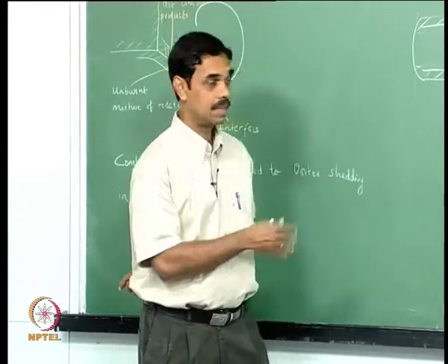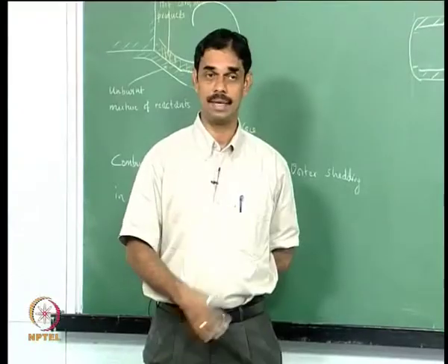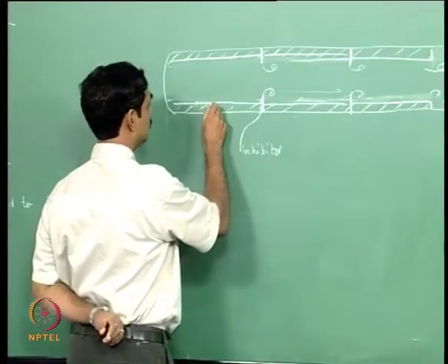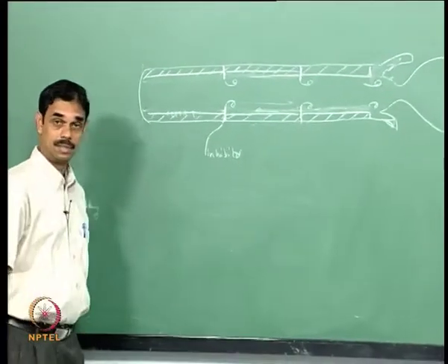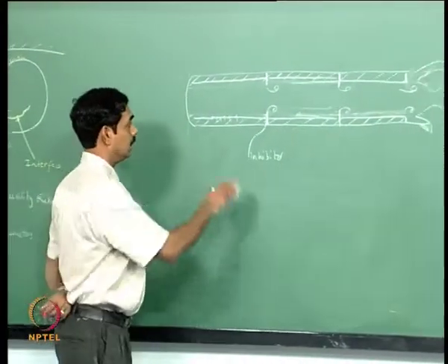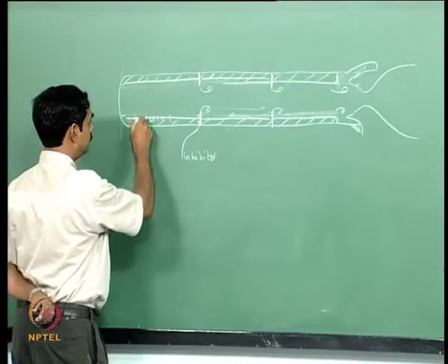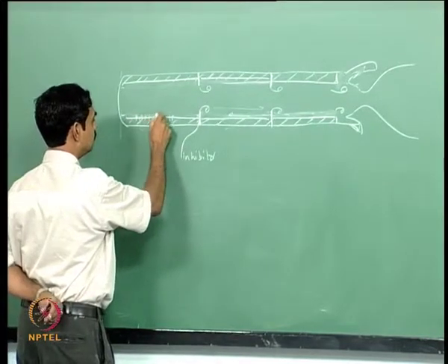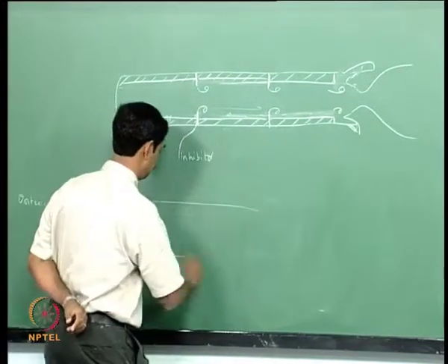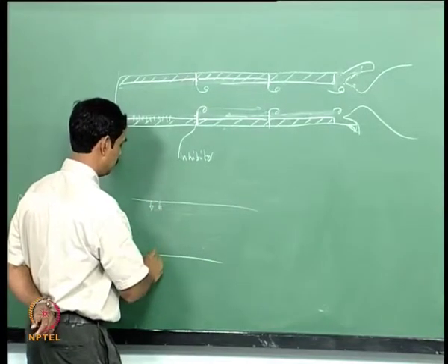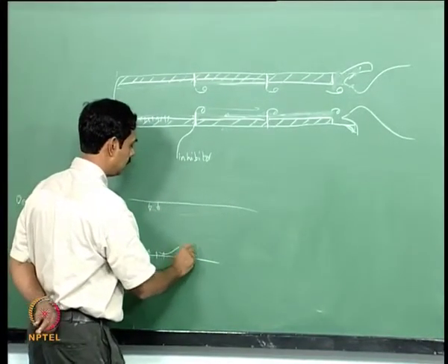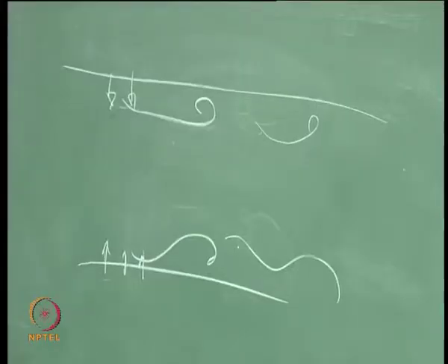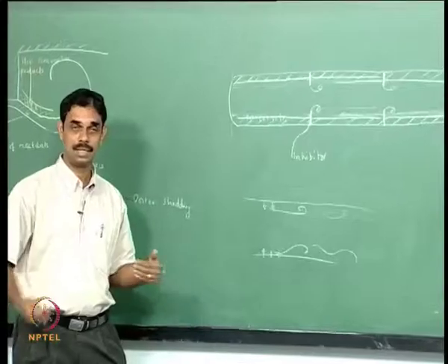So here is another case where this coherent structure is creating a problem, but it is more like an aerodynamic instability. So we are not having combustion happening just over the propellant surface. Now even if you do not have these inhibitors, propellant burning is like a radial injection. So if you have a situation where you have gases coming out this way, eventually there will be vortices being set up, because this flow, the radial injection flow, is an inherently unstable flow.